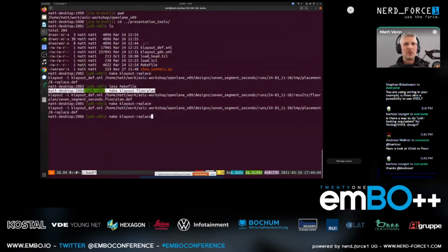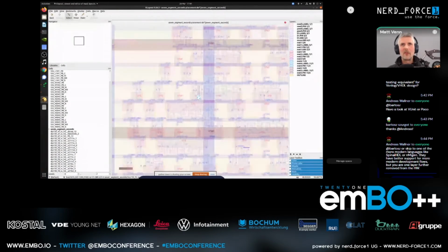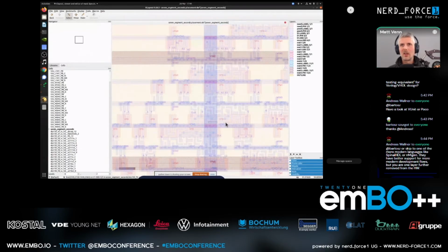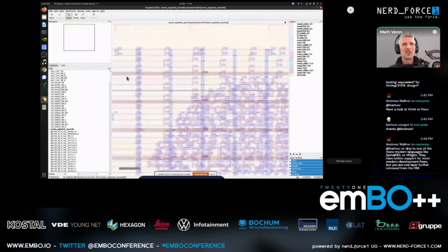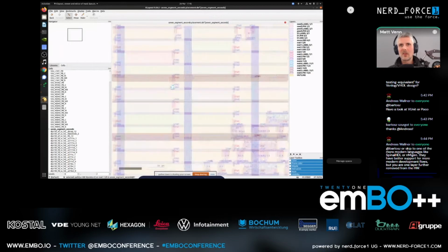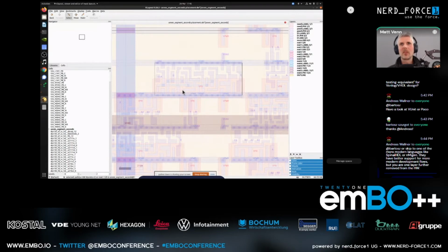And then we do the finer placement. So now everything is lined up. So we see the value of this kind of modularity. We've got ground and plus, and they're connected together with this power grid. So these horizontal and vertical lines connect up with these vias onto these horizontal lines, and then everything bonds onto that. The cells are flipped on top or bottom depending on where they're matching up to, so we can connect them all up and get them nice and dense.